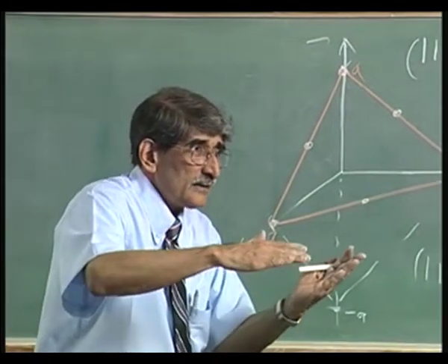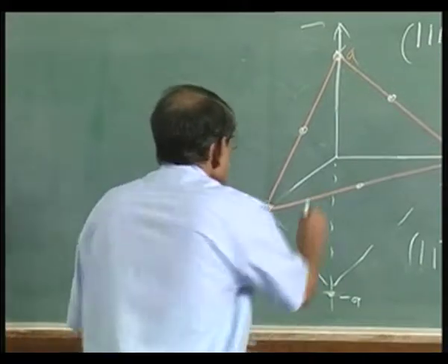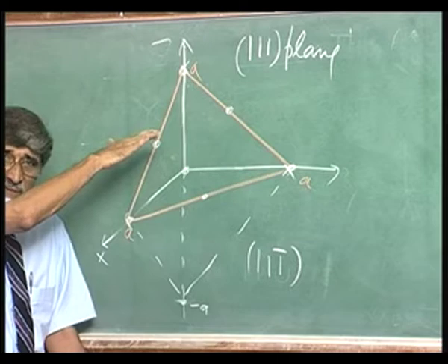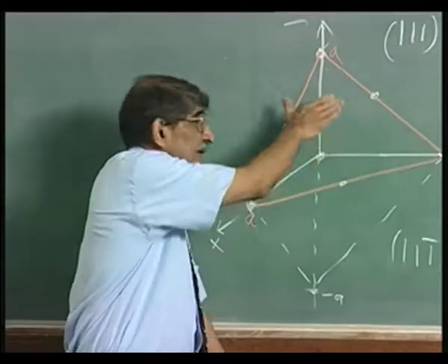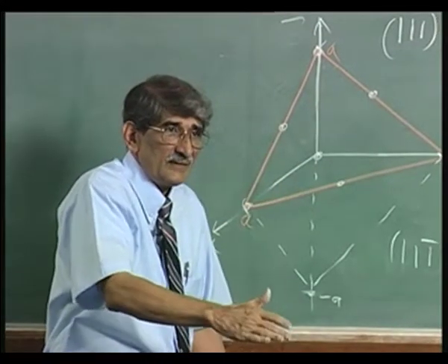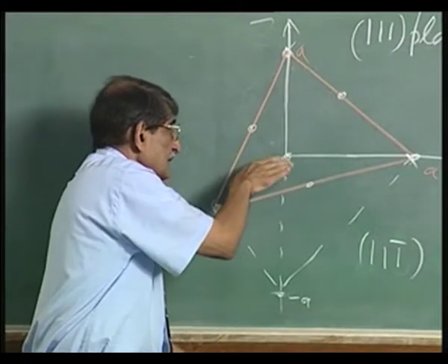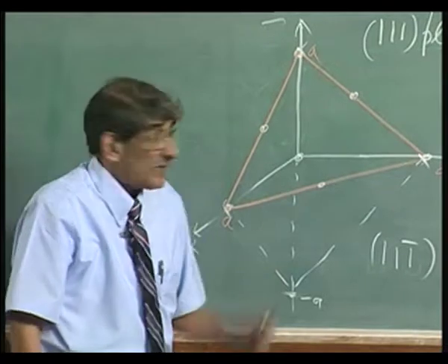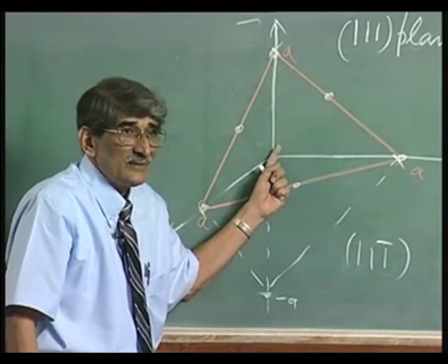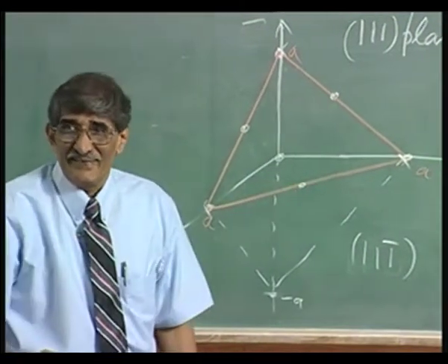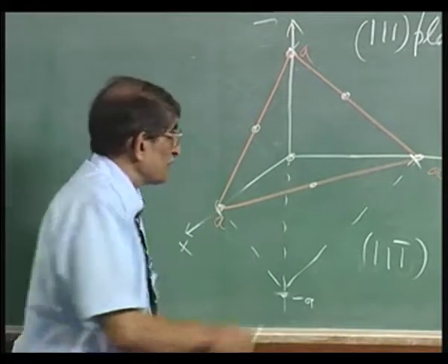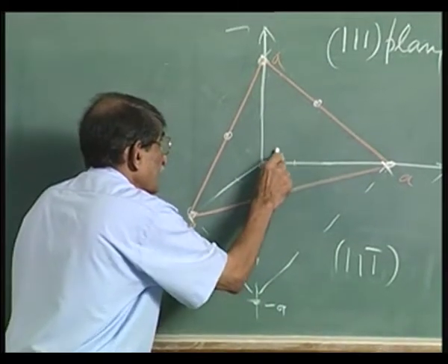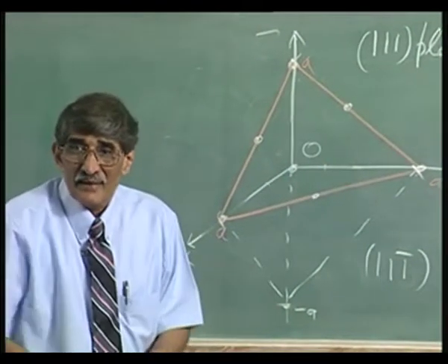You have got another plane which passes through this. You can draw another plane parallel, that is 1, 1, 1. Whatever is parallel to this is the 1, 1, 1 family. So, I can draw parallel to that passing through this, that is 1, 1, 1, that is arsenic. In between these two, you have got a gallium plane, correct, because this is A, but A by 4, A by 4, A by 4 if you take, that is that atom, gallium, that is this atom.